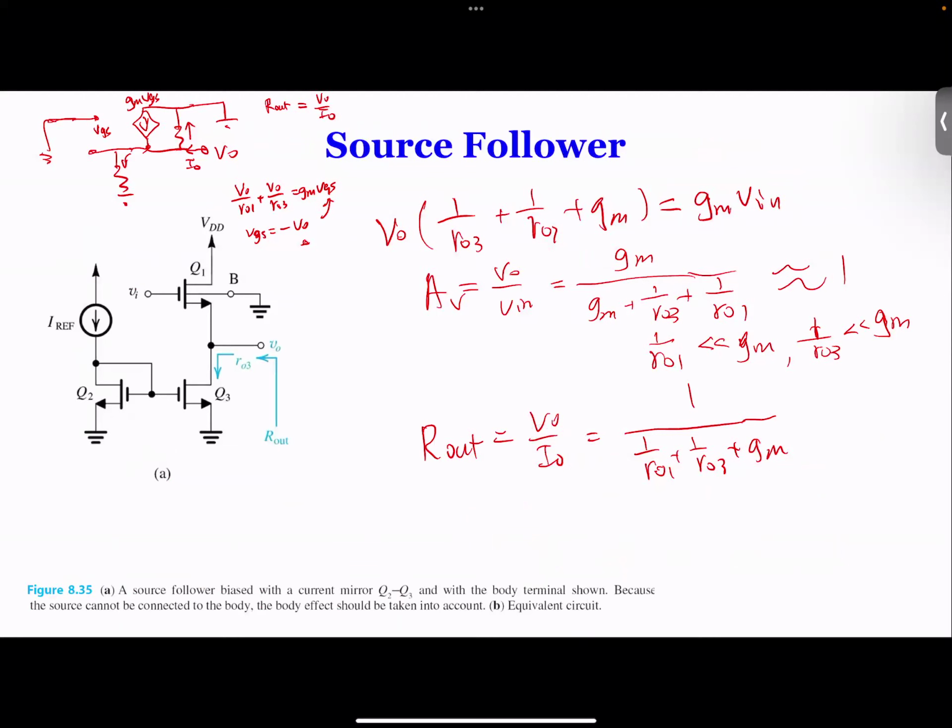This one? Yeah, so are you able to overhaul this right here? Or will you just replace that with... Oh, that's because we did the current source analysis before. We find that the whole thing doesn't matter. Only this one, resistance matters. Oh, because the current gain is 1 basically. Yeah, the current gain is 1. Only the output resistance here. That's why it's all connected. Right. So as we move along chapters 9 and 10, you will slowly feel that all the things are going to connect together. All the pieces are going to connect.